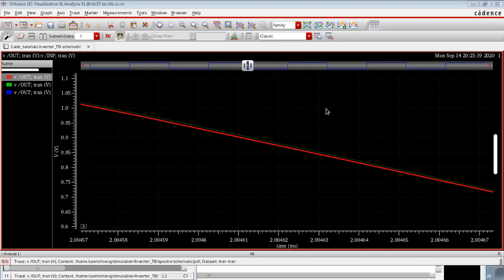Yeah, it's quite better when you just totally elaborate it with about specifications. But one thing is, if in the case of PVT analysis, I find a little bit any kind of discrepancy, then I have to go back to the schematic again, right? Yes, you need to tweak some of the parameters, like due to process variation or temperature variation, some of the transistors may get out from saturation. So you need to tweak it such that in every corner. So yeah, it's an iterative process.